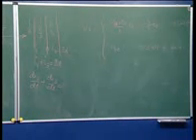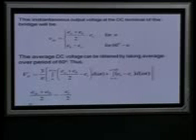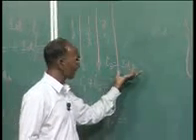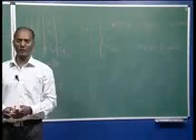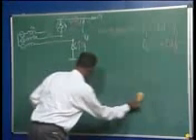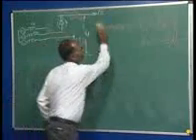So this is the voltage that we have written. Now to take the average voltage, as I said, this is for this period. Symmetrically we are getting it for the other period, and here again 60 degrees. So our average voltage we can write as usual for only the pi by 3 degree period, and that will be giving your output voltage.